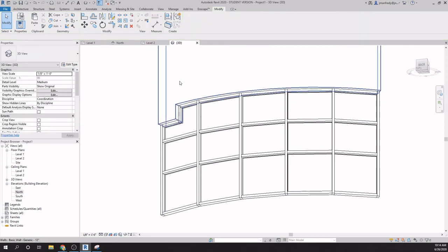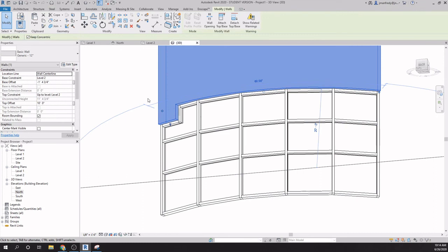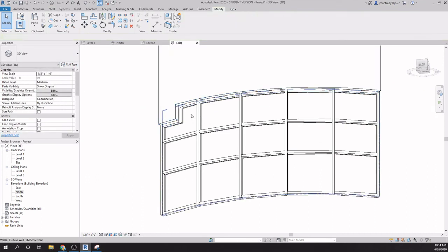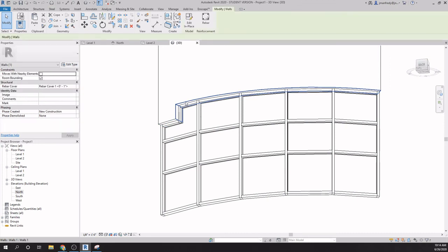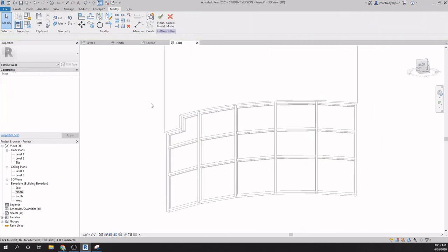Voids are invisible. So this is the wall right here in properties. That's not the cutout. You can't select the cutout here because there's no way to grab its edge. So typically you select the edge that it impacted, that it removed. So right there, you put your mouse here and you select that edge. Notice the entire wall doesn't get selected, just that edge gets selected. Then you can edit in place, so it lets you return to that 3D object. It's still here, but it is invisible.